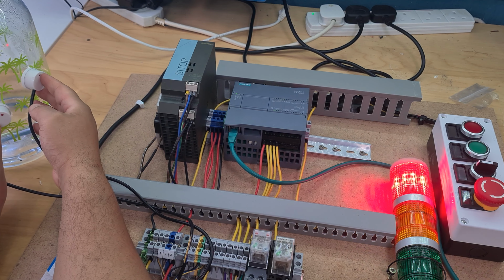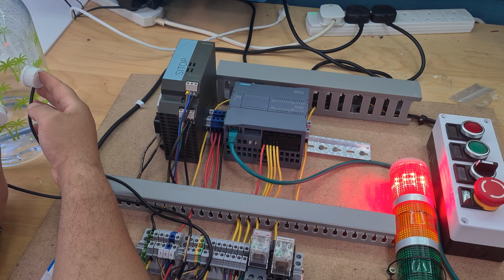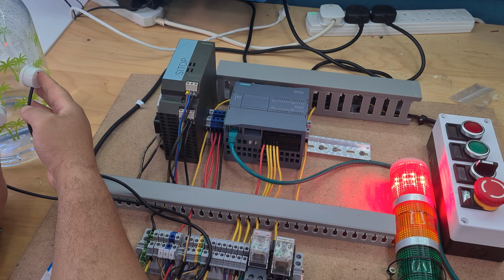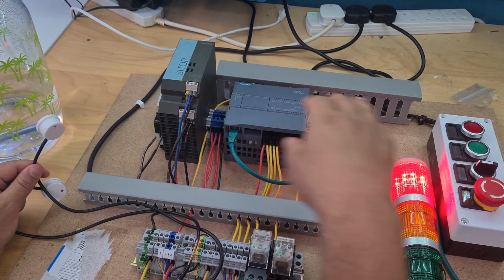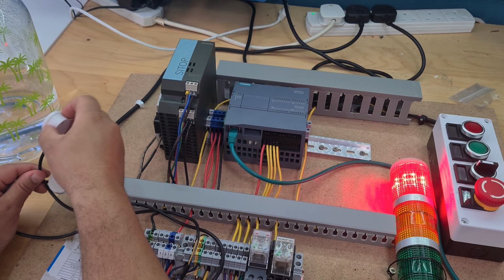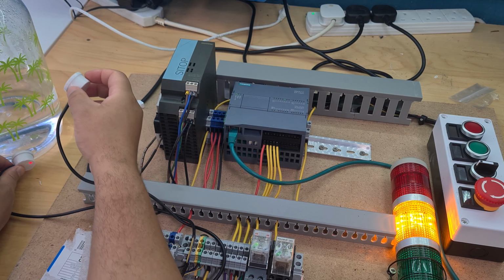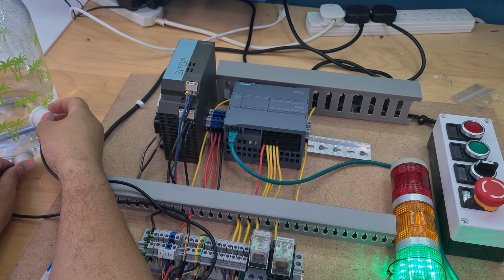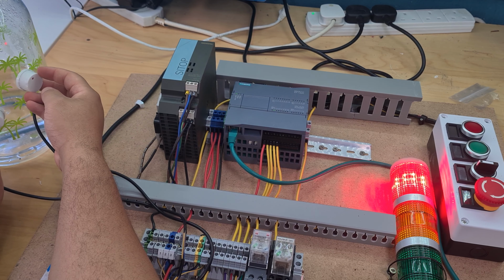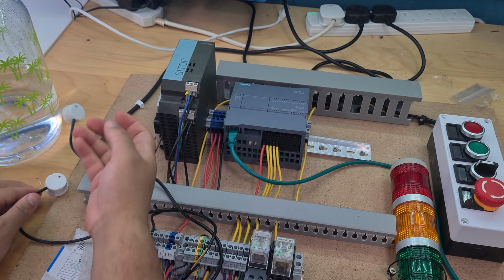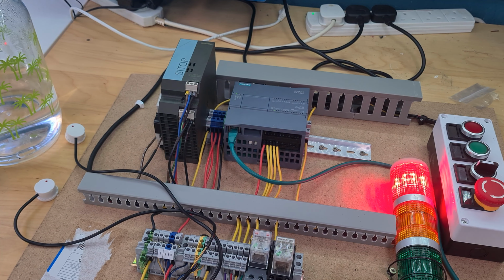I'm going to lose my low level now, and there you can see I didn't get a fast fall detection. It hasn't started going into its error mode and flashing the red light. Now if I reset this and I get my low level back, and then I have my high level, if I lose my high level and then lose my low level too quickly, I end up in a fast fall detection. So let's run through the program. That's how it works. It's a very simple program, but it works very, very well.